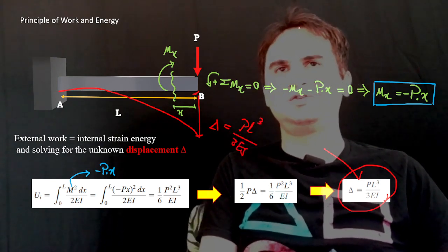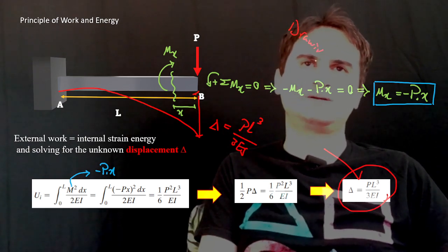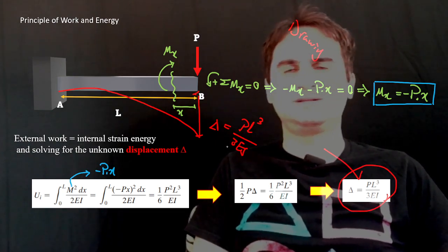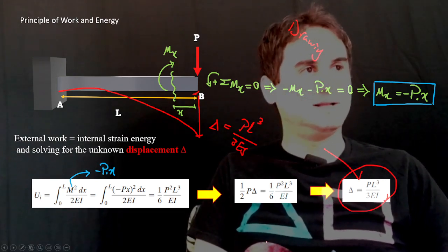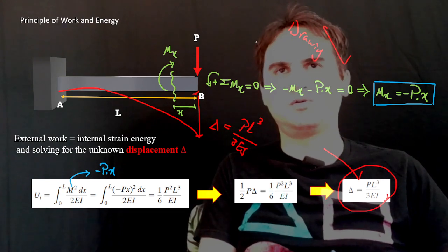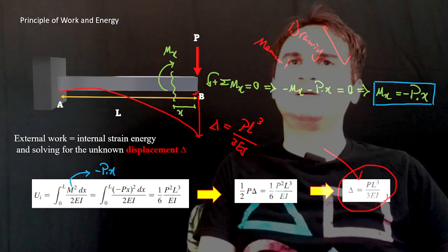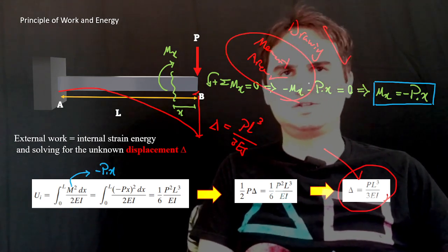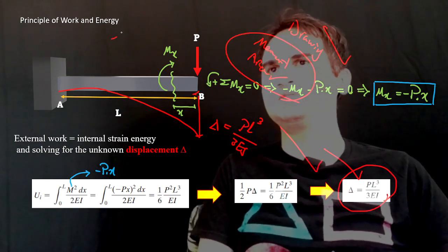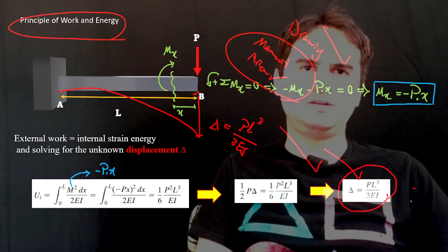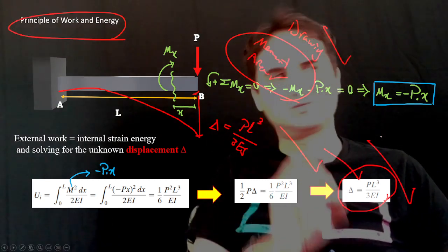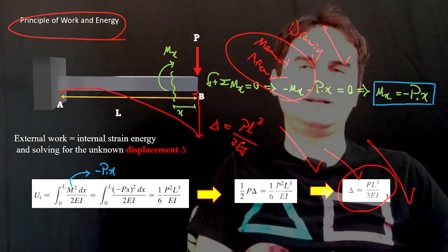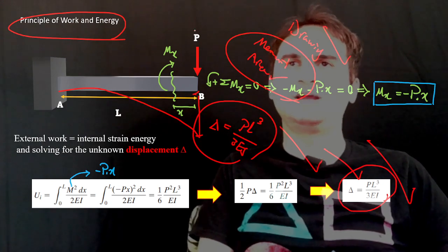You can use the drawing method from mechanics of solids for creating the shear and moment diagrams, then theta and then delta, or the moment area method, or the integration method itself. The energy method just gives you a direct answer for this question. So that's a kind of singular approach to calculate the maximum delta at the free end.